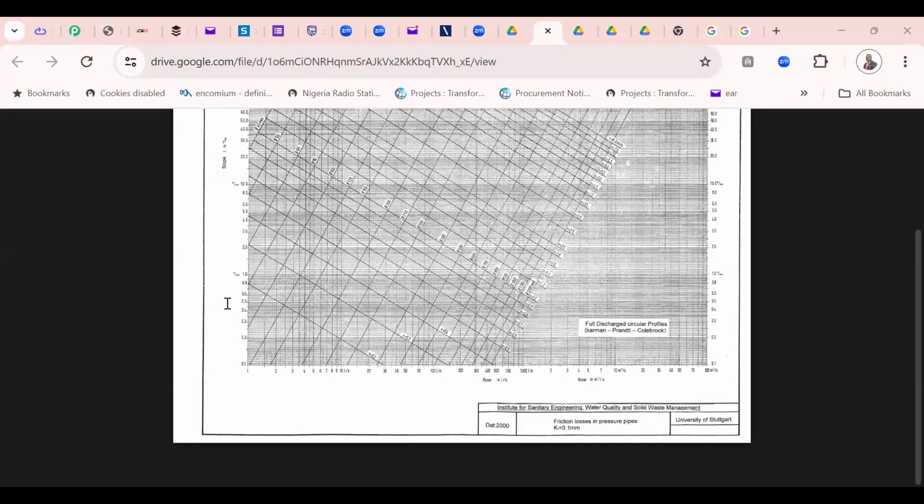Now, this slope, and that is the only thing you need to understand about this chart. The slope is calibrated in per thousand, not percent. Percent means per 100. Per thousand means per kilometer. So this chart is calibrated based on per thousand. If you say slope of 0.5, what we're talking about is 0.5 per thousand. I want this to sink: 1,000 meters, or 1 kilometer.